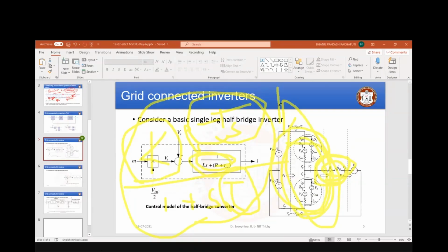Like you will have your converter as some first order differential equation, and this extra term, the RL, they will add as a consecutive term. They will take this also as a separate first order differential equation, and this one also separate. So once you get these functions, based on that, you have to tune one after the other. Earlier, they used to give only current control.